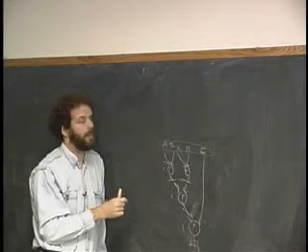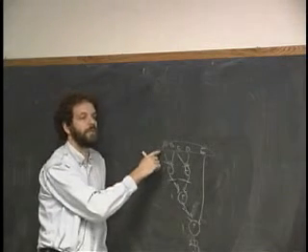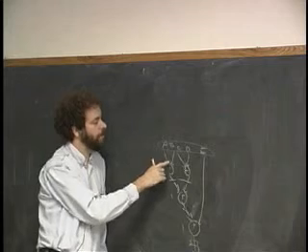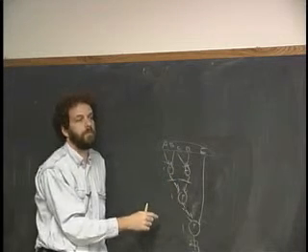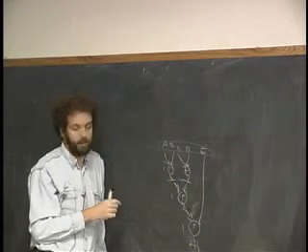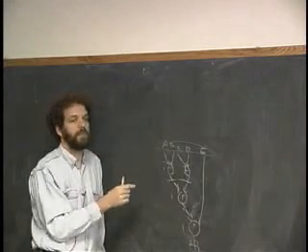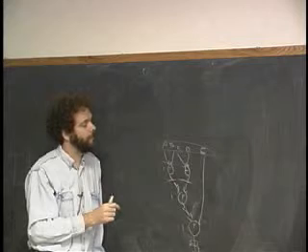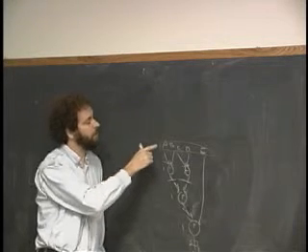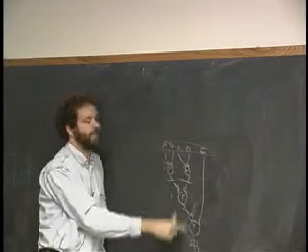Okay? So what we want to do is ensure that there are the same number of registers between all the inputs, whichever ones are used, and every input to any part of the circuit here. And it turns out that you can ensure that that's true if the number of registers between any input and the output are the same. This is kind of a neat proof for you guys to do on your own.